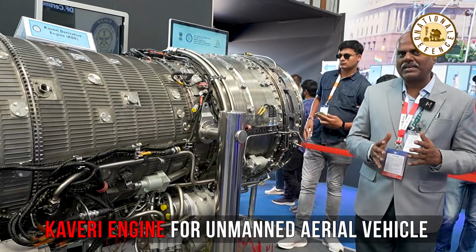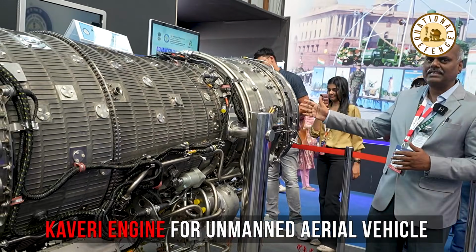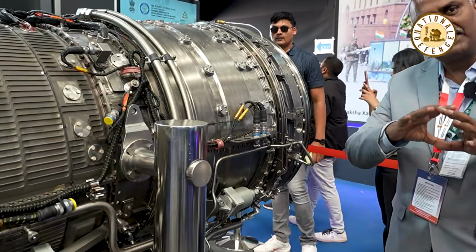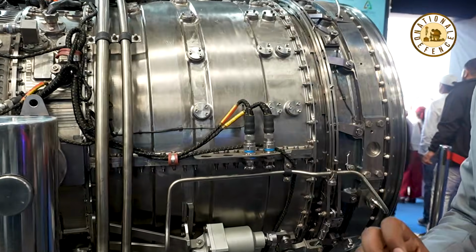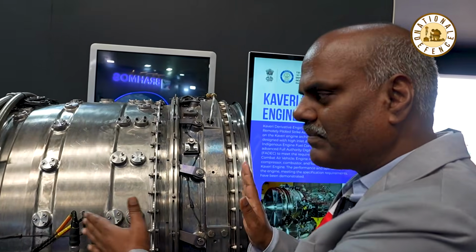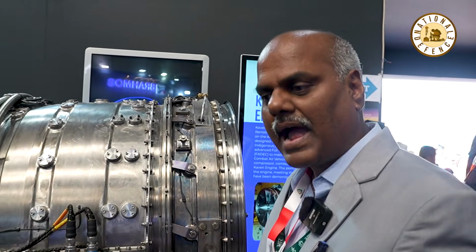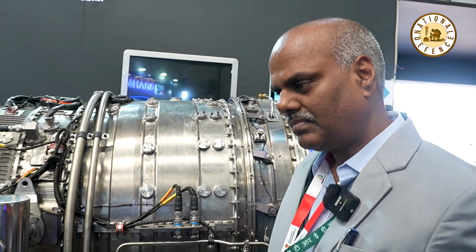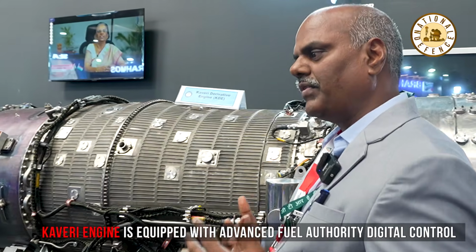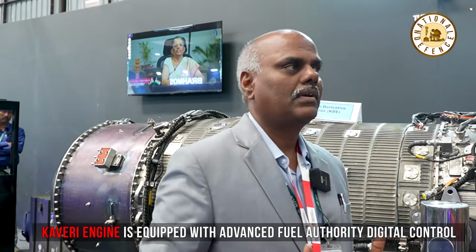The unmanned combat air vehicle specific technology includes a new fan with variable geometry, because the unmanned combat air vehicle will have a serpentine air intake, so it should be distortion tolerant. And this is an autonomous air vehicle, so we should have an advanced full authority digital control, which has been done, and we have made it more reliable with a cross-channel data link.